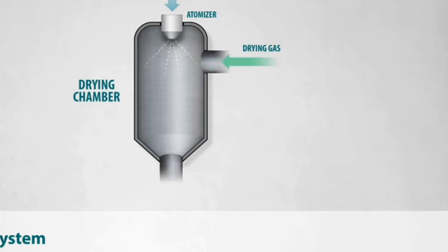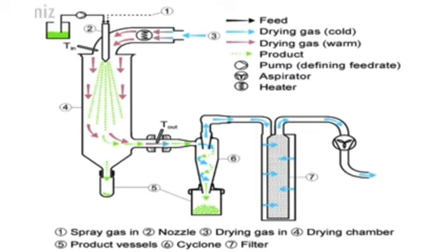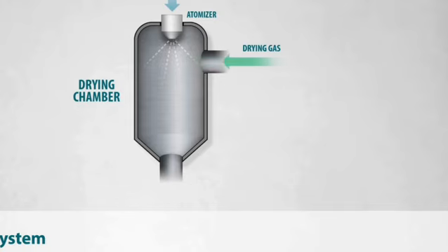The mechanism of spray drying can be divided into 4 main stages. First is feed preparation. The liquid feed, whether it's milk, fruit juice, or eggs, must be clean, uniform, and suitable for drying. The liquid is filtered to remove lumps or impurities, similar to how you might strain fruit juice at home to remove seeds or fibers.